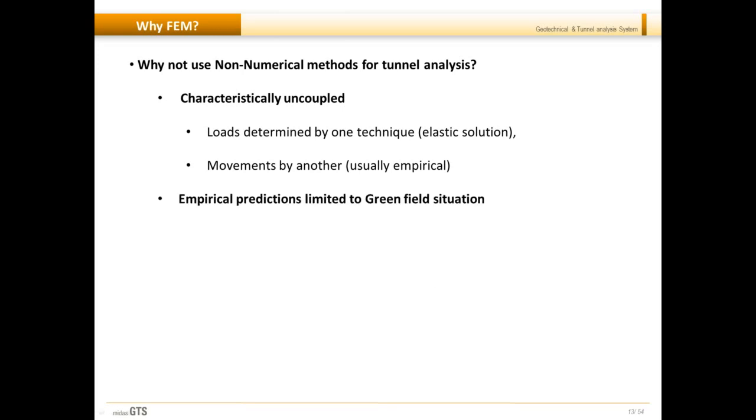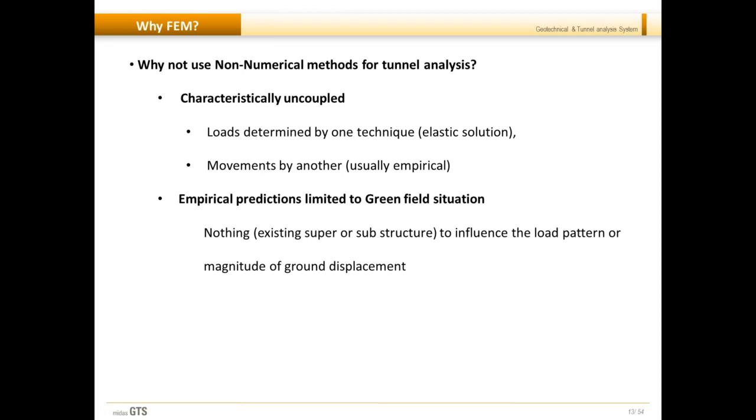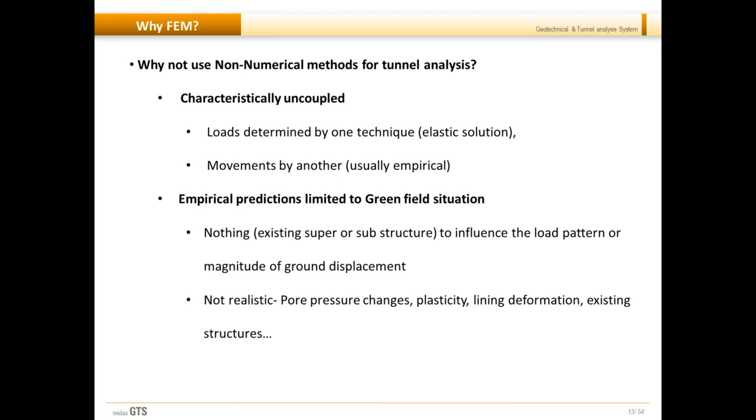Then another major limitation with these non-numerical methods is that their empirical predictions are limited to greenfield solutions. This means that they completely ignore any kind of load pattern that could possibly affect the tunnel excavation. So they assume that there is nothing existing other than the tunnel itself. There is no superstructure or substructure in the vicinity to affect it, and they are not realistic because they don't consider the pore water pressure changes, the plasticity behavior of the soil, the lining deformation, the existing structures and their effects.